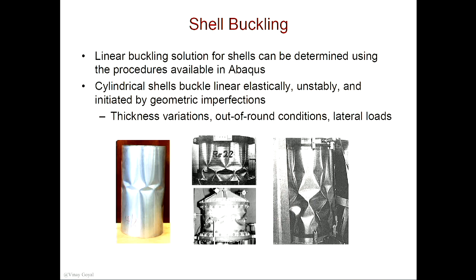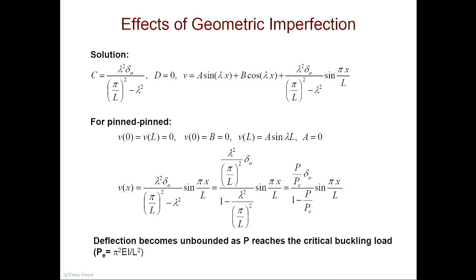The bar example, as you can see here, as I'm approaching PE, I'll get the beam to buckle. So there's no question about that. And that's not going to change. So the imperfection I put into my system is not going to change the answer for when this beam is going to buckle. Because when P approaches PE, you buckle it. So there's no question about that.